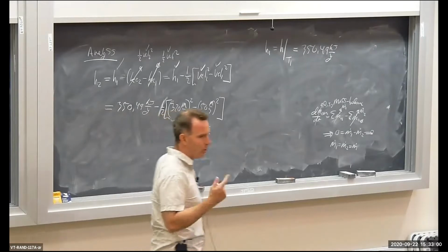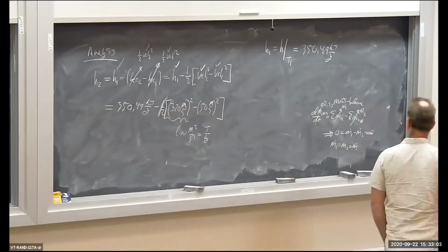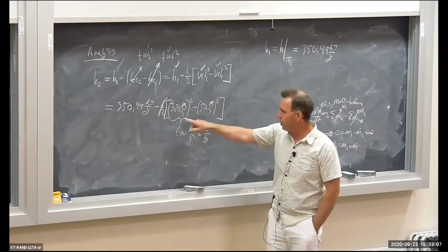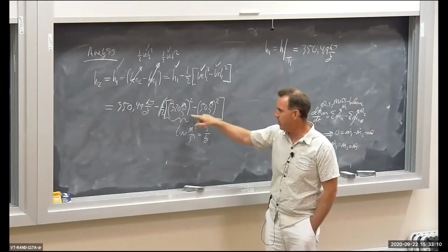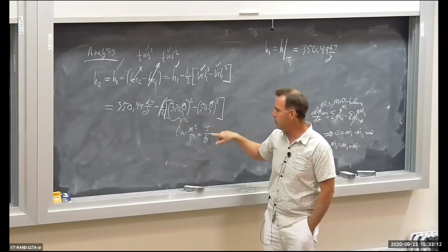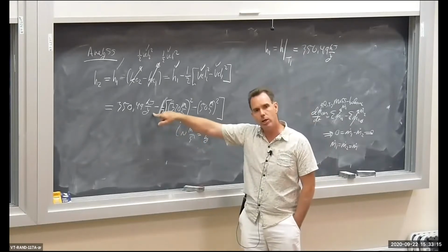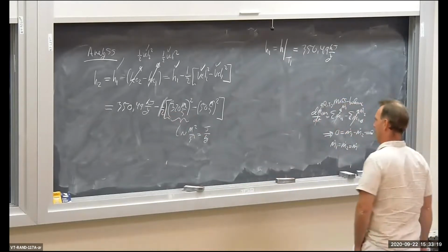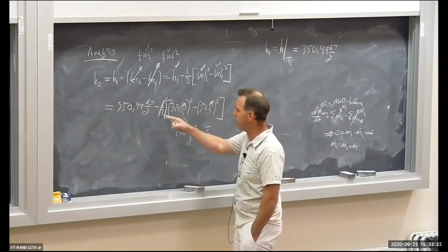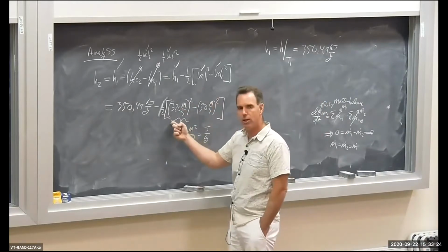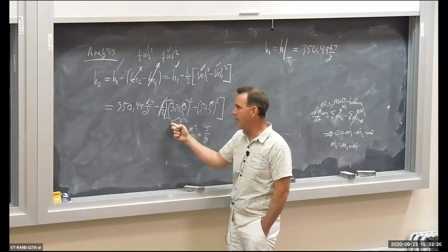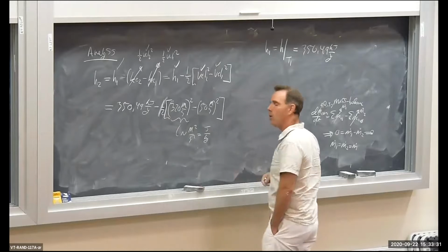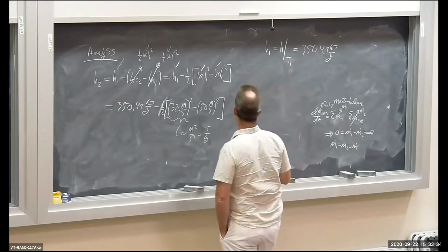Think kinetic energy, 1/2 mv squared. The velocity squared terms have units of joule per kilogram, whereas specific enthalpy is kilojoule per kilogram. So when you do calculations involving kinetic energy, you need to convert the joule per kilogram into kilojoule per kilogram, especially if you have an enthalpy or some other property in the equation.